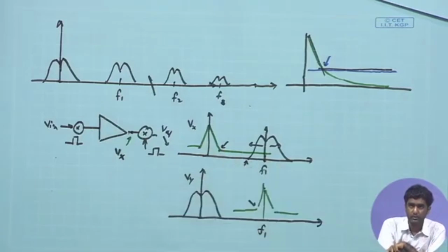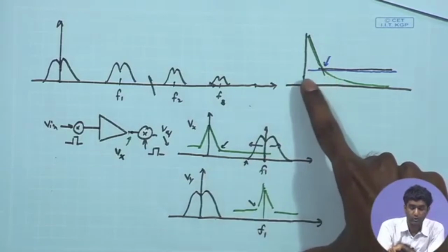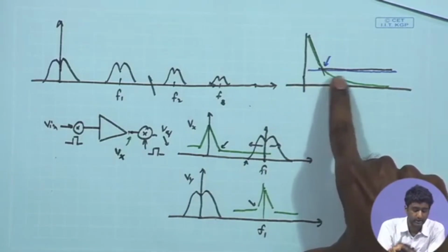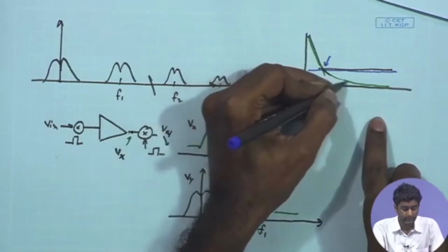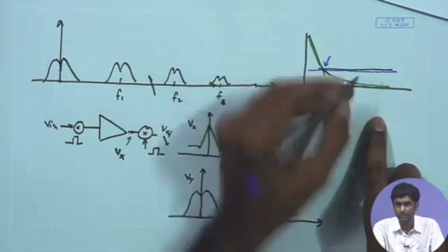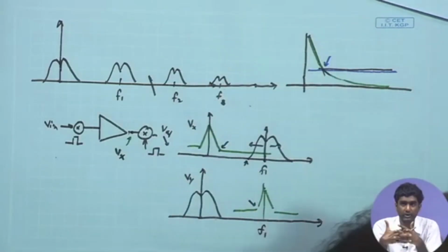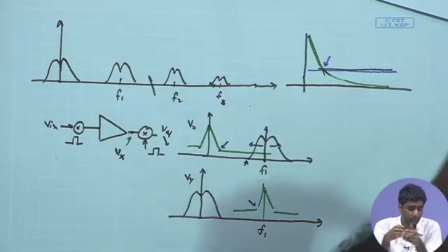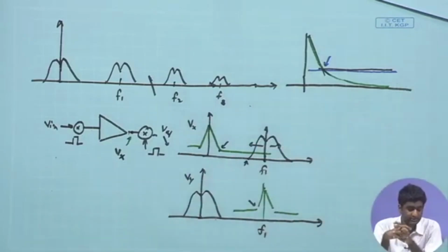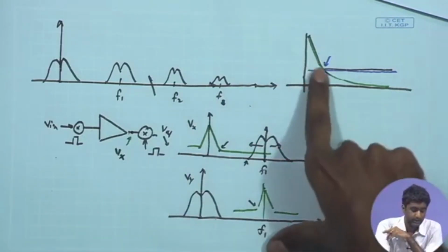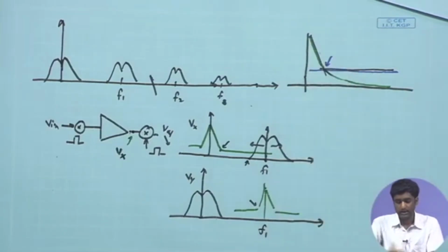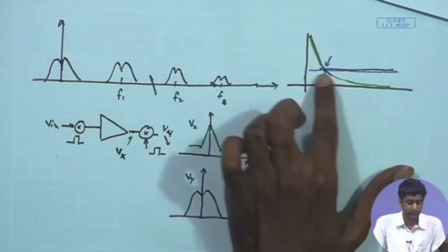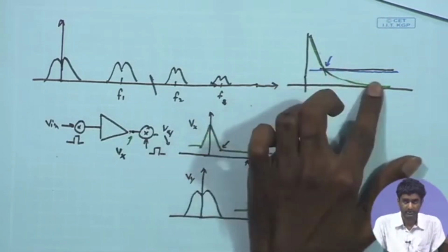But if you are more greedy, and want to be even better in terms of the 1/f noise or overall input referred noise, we would like to push the signal as far as possible, so that even the tail effect of this 1/f noise is not coming up and affecting the signal. Because remember, when you are talking about high precision signal, 10 bit, 11 bit, further higher 16 bit of precision, even this tail effect of noise which is increasing your overall noise can be important to address, and we would not like to have even this tail effect corrupting our signal.